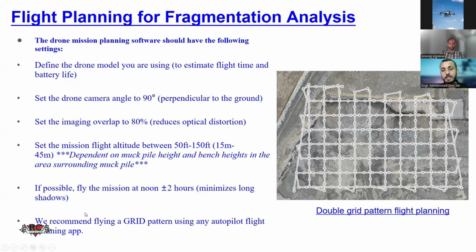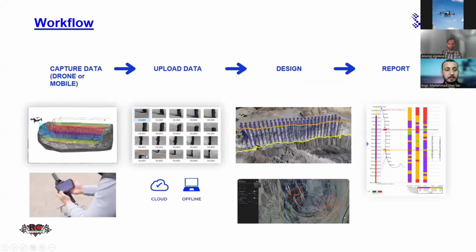Yeah, and about the mission planning on the ground, it should be a grid pattern, crossing each other, so that we can get highly precise data. And there shouldn't be any area left unstitched, like potholes. For that, you just need to take imagery from the drone. You need to fly the drone over the site which has a mining pit, and just upload the data on the Strayos platform.